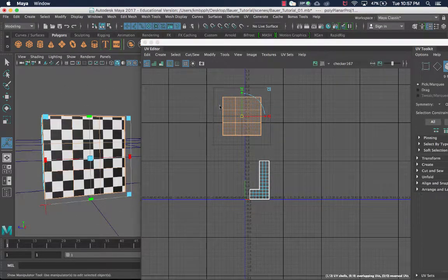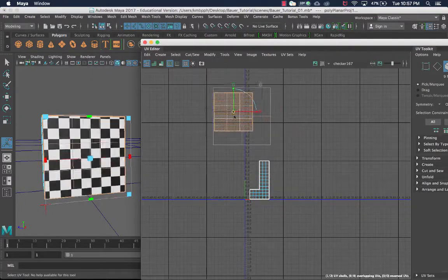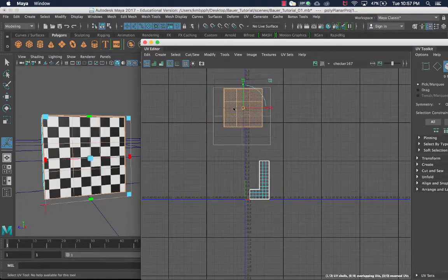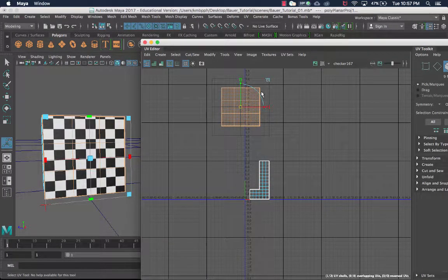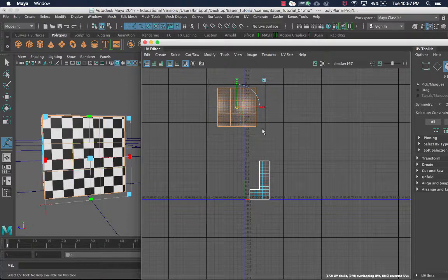Now you'll also notice that if I move those faces around, it moves the checker pattern over on my cube. And that's because we're just moving how this map is being projected. We're moving which part of that map is there, and we're messing with the UVs. The UVs are what's kind of making that projection for us. So I'm going to leave that over here. I'll leave that alone, and I'll just click off of it.